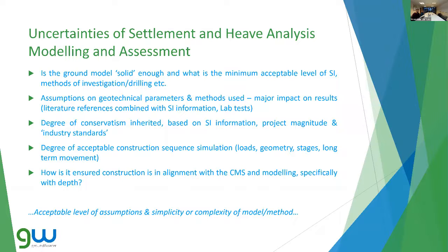Another thing is to look at, when it's actually come to construction, how in alignment the actual construction is with the construction method sequence and the modelling, specifically with depth. I believe in some London boroughs at the moment, there are even auditors walking around making sure people are sticking to their construction method sequence. And if they're not, they're told to halt all works and completely stop, which obviously can cause delays, expense, and a whole host of issues.